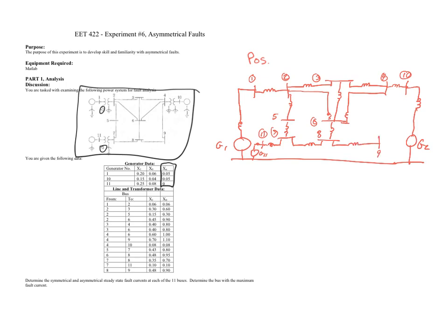And so now the final connection we have is between bus 8 and bus 9. And then there is also a connection between bus 4 and bus 9. So that is your positive sequence diagram showing the power supplies and all the impedances that interconnect. To get a sense of what's happening with the interconnections, just know that this is the impedance Z1 to 2.